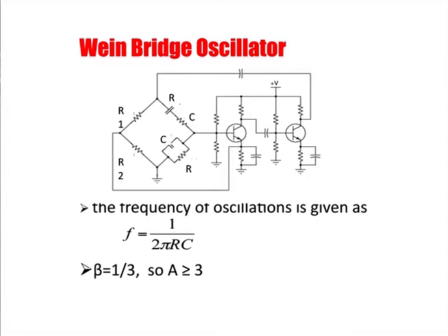So, when the oscillations are obtained at the output, they will be of the same frequency for which the feedback circuit is producing a phase shift of 0 degrees. Therefore, in both cases, the RC phase shift oscillator as well as the Wien bridge oscillator, we find that the frequency of oscillations at the output of these audio oscillators depends upon the feedback circuits. So, by varying the value of R and C, we can vary the frequency of oscillations.